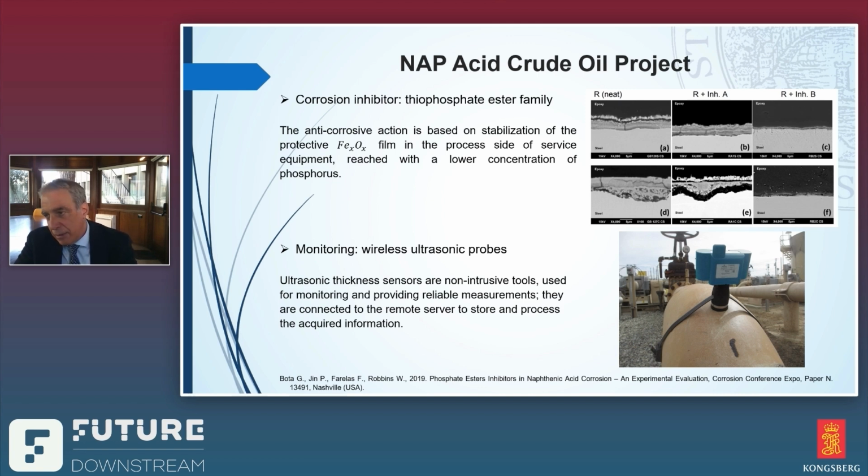Normally, with ultrasonic testing, we cannot measure the thickness if the piping is in service, because the temperature is too high. With these probes it is possible, and so this gave us the possibility to monitor the corrosion.